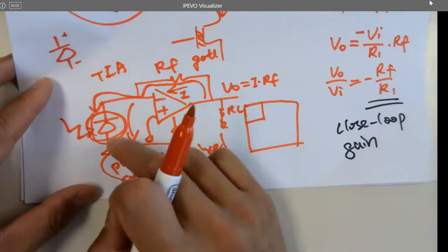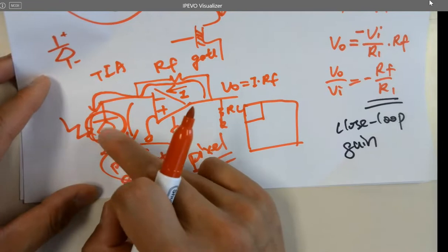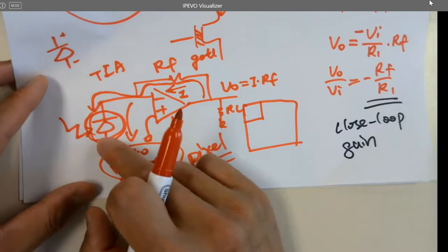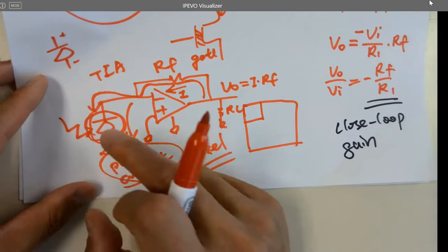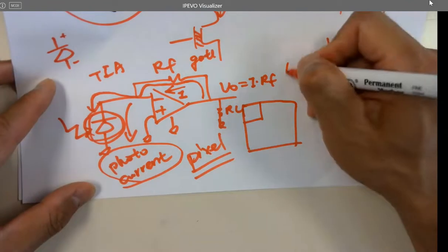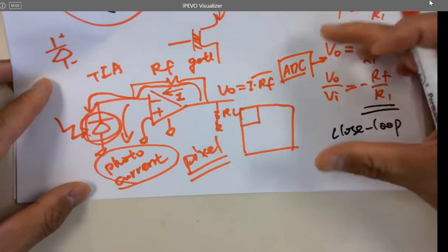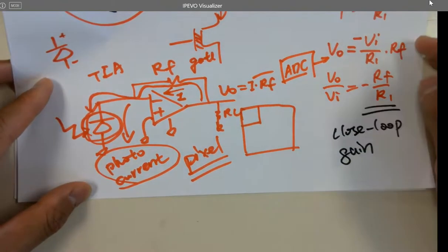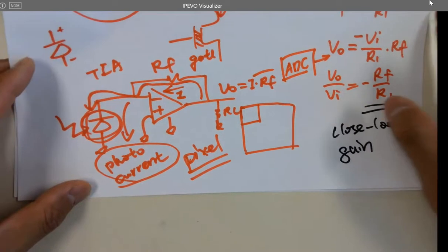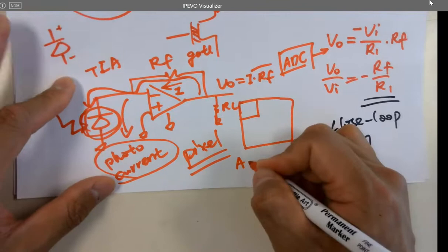And it's used for amplifying photocurrents, not just from the photodiode, but also PMTs, all different photosensors, whatever generates photocurrent. It's going to be amplified and converted into voltage, and then the ADC. Okay. Whenever you get a digital signal, you can do whatever you want with the FPGA or any other digital chips. Oh, aspect ratio. I just remembered that name.